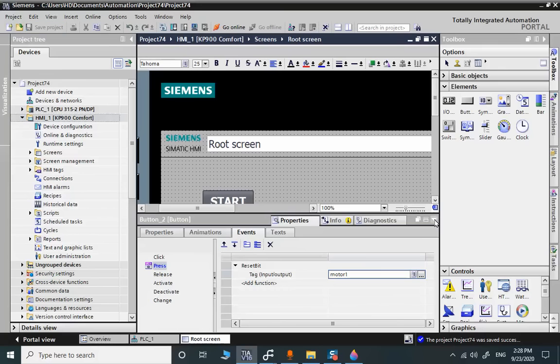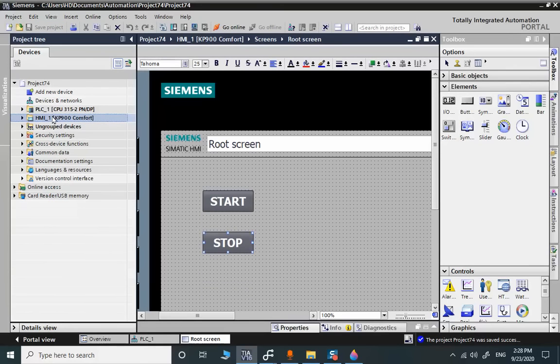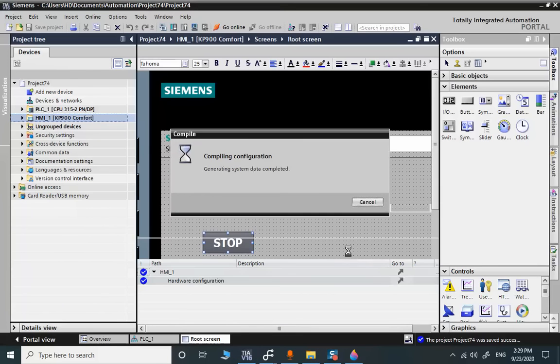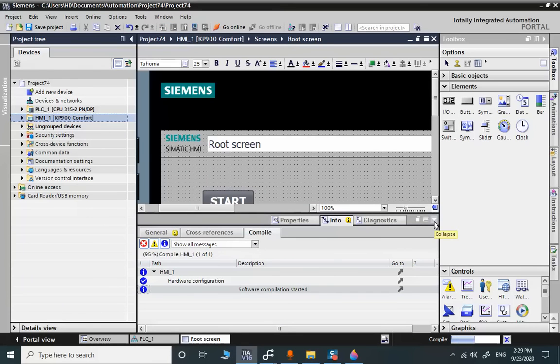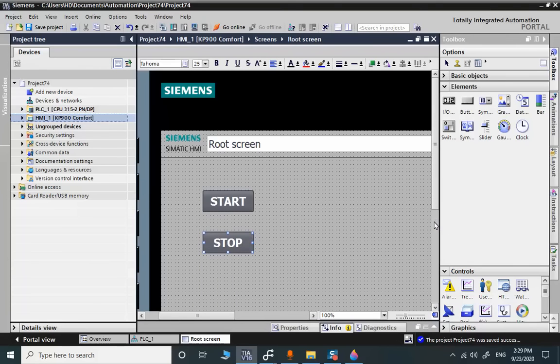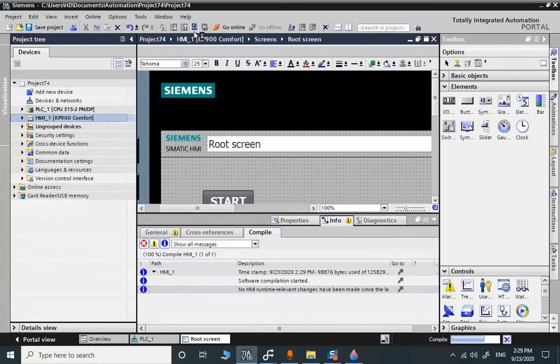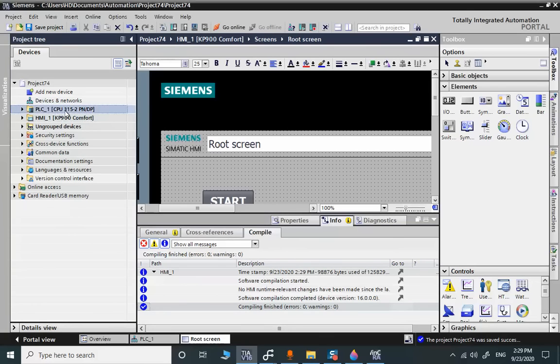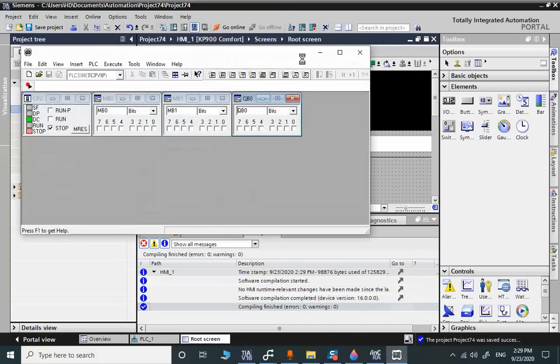So let's compile the HMI program. By this simple program, you have the chance to set and reset a channel on the PLC directly without any interface to the user program. We will go online on the HMI. Here we don't have the actual CPU. We use simulating module for the PLC. For that, you need to select the PLC and use the simulation module.